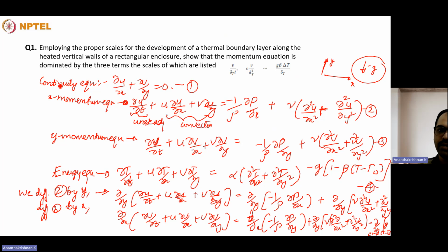So we had employed the continuity equation, x momentum and y momentum. We didn't use the energy equation, I just wrote it down to show that it completes the set. Because the temperature equation is implicit, you can explicitly find the temperature once you find the velocity from here.